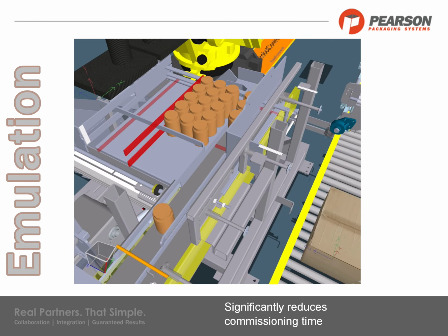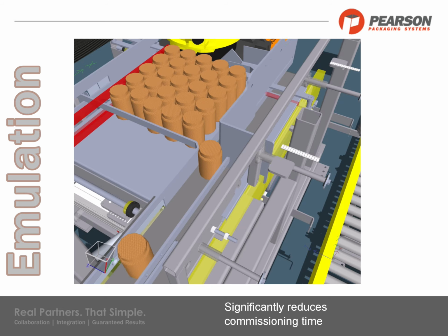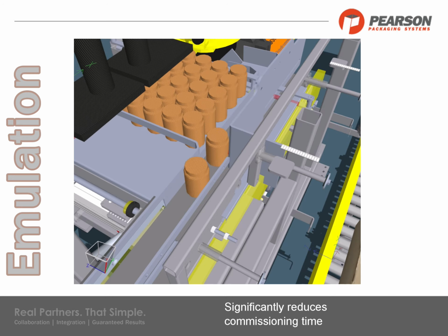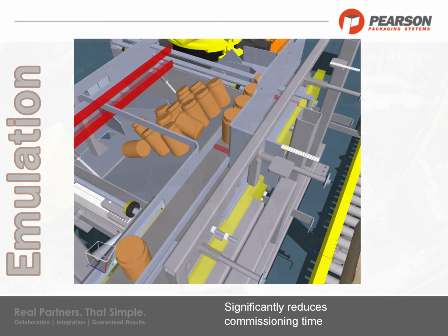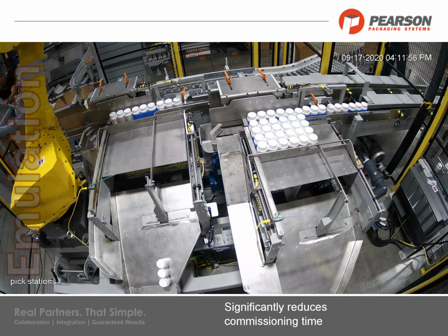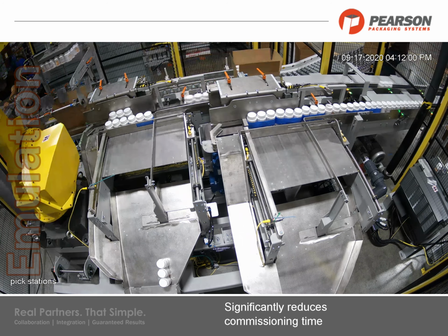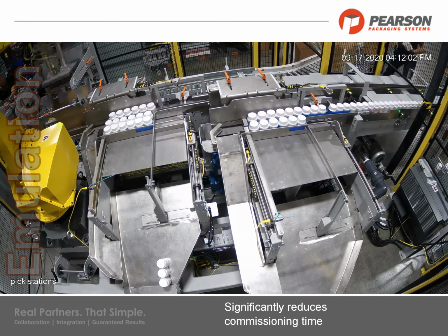If something were to get tipped over or not picked up by the robot for some reason, there is a method to clear that out and allow it to continue to run. And lastly, we'll point out that there's a little blade stop between the lane of infeed and the product that prevents it from pushing out or getting tipped over when the pattern forming area is cleared.